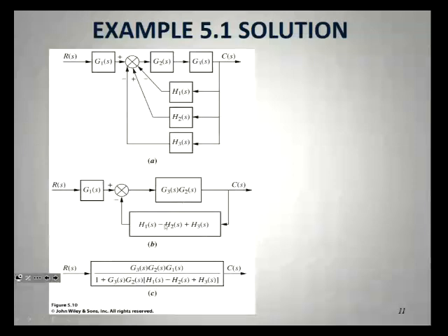That's just doing G over 1 plus GH. You've got G on the top line, including this one, of course. But the GH part's just the bottom part. In fact, you could leave that bit out. The easiest thing to do is leave anything to the left-hand side out of the equation at the beginning. So just do this bit first. Just let me write. So we've got G will be G3.